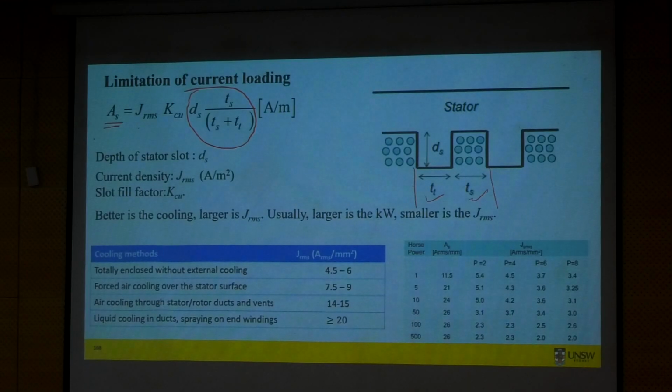And if it's automated, as in a winding machine where the conductors are wound around something and then inserted, even an automated machine tends to leave a lot of space in the slot. The factor by which the slot is filled is referred to as the slot fill factor.